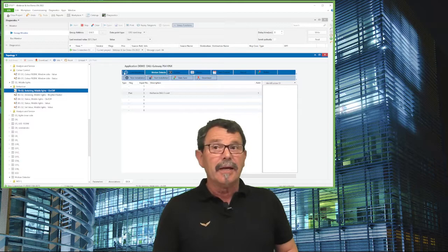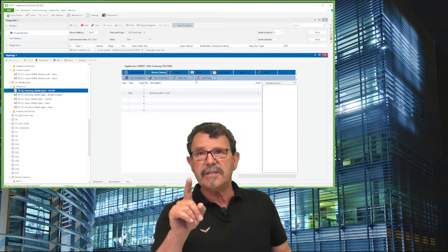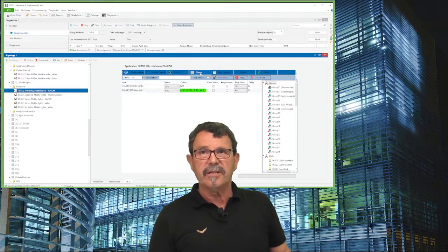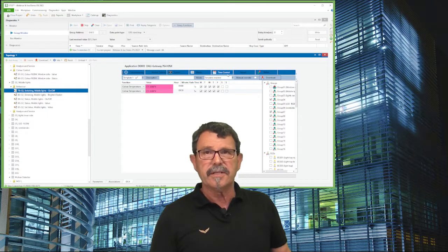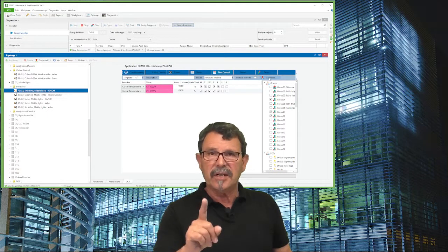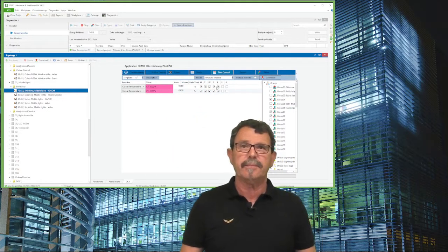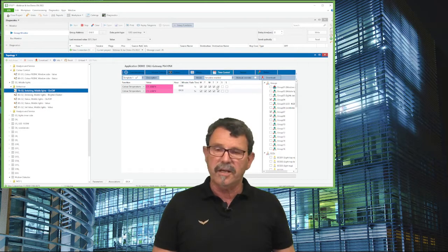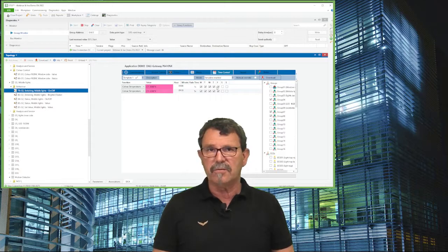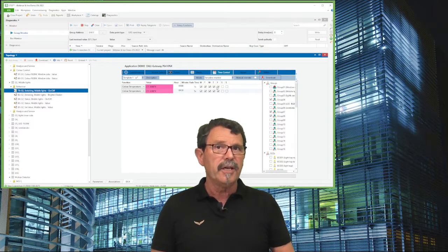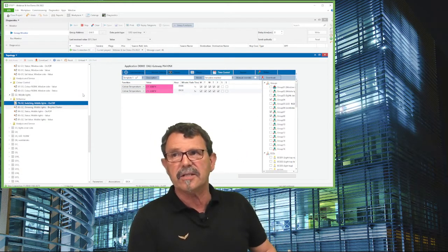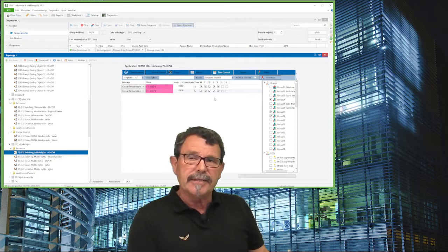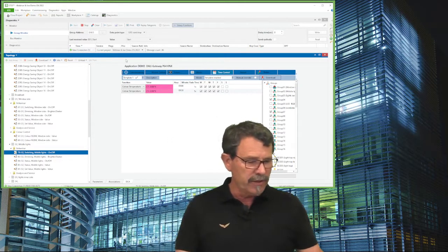Get started with it. What is important, whatever you are doing here in this DCA, whether we talk about sensors, scenes, effects or the time control, don't forget for each function to download your settings, which you find exactly here. Separately download time control, effects, scenes, and so on. It is stored, it is filed in the Multi-Master DALI Gateway application itself. So don't wonder if it doesn't work if you haven't done it before; at least at the end, download the full application of the DALI Gateway. You get me? Fine. Yeah, well, and so let's get started now with the practical part.